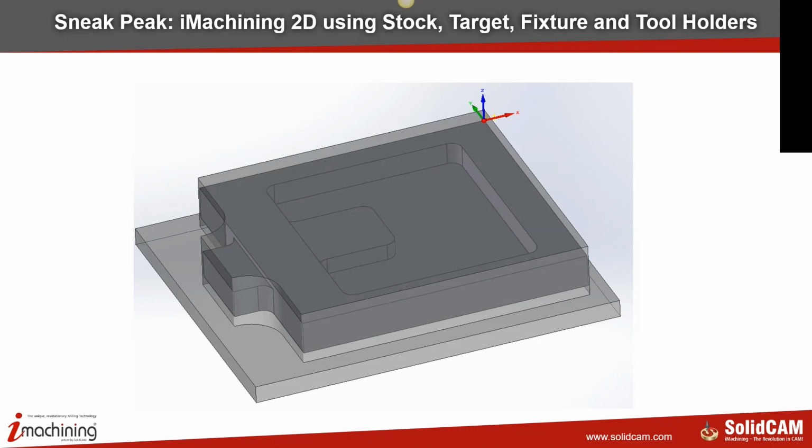The first thing here is iMachining 2D using stock, target, fixture and tool holders. Basically, we are using a merging of iMachining 2D and iMachining 3D, which means you can pick faces that you want to machine, and then we will use all of the 3D model geometry to set up everything for the user. We will look at the updated stock, we will look at the target, we'll make sure we don't gouge anything, we won't hit the fixture, et cetera.